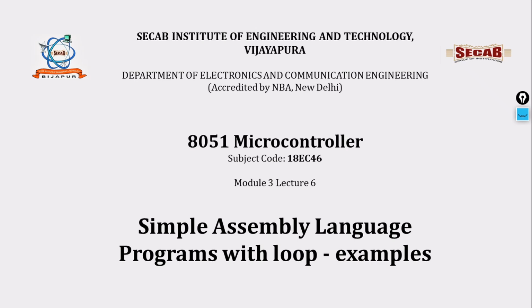We went through the different data sheets to see the machine cycles required to complete an instruction. Some instructions take only one machine cycle, some take two machine cycles, and some take somewhere around four machine cycles. Based on that, we looked at how to calculate the delay.